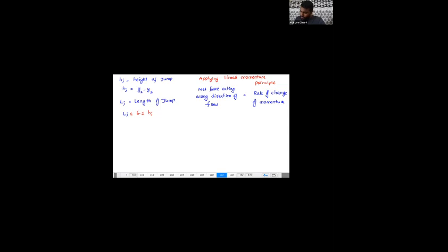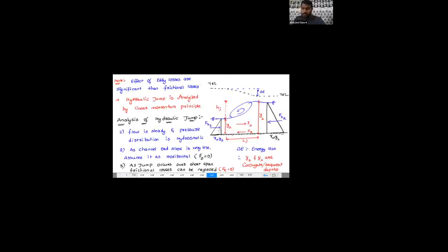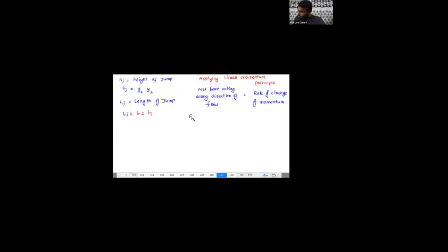Okay. So what are the net forces acting over here? Tell me. If you see, you can say the forces as FH1 plus FD minus FR minus FH2 is equal to the rate of change of momentum, means rho Q into V2 minus V1. If you have any doubt, you go back to uniform flow, where I mentioned how this rho Q also came.